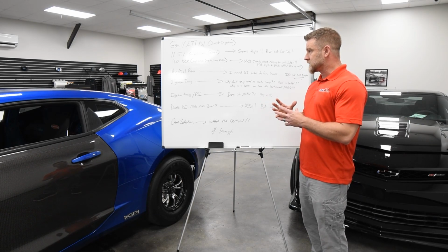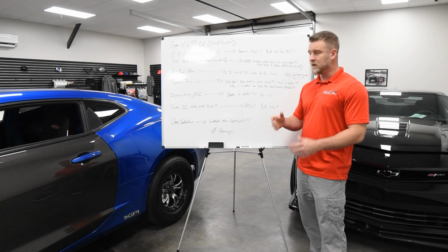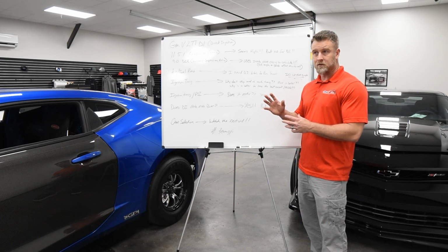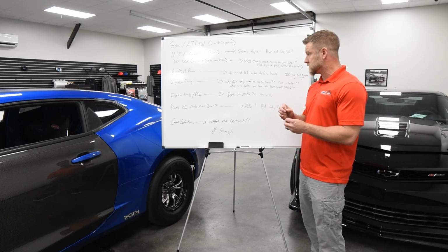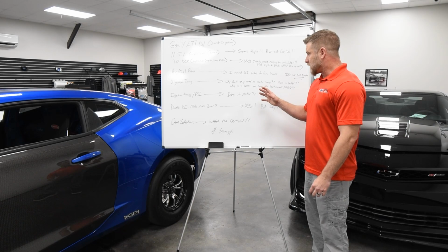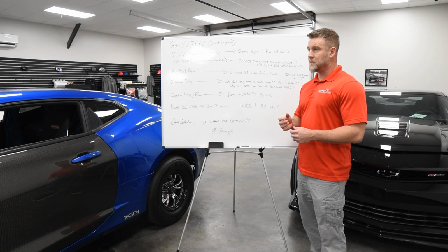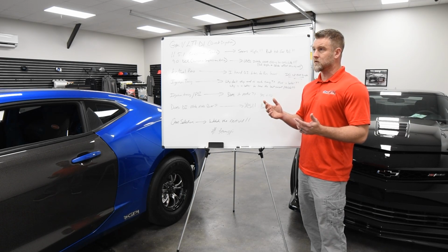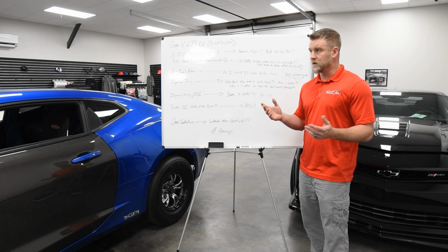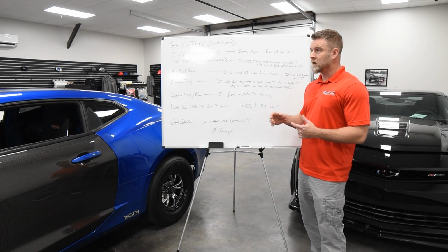When you have a package that is more efficient that you can fire later and make max power on, it's going to be better. And I'm not talking about getting abusive to the point of being way over timed, 3 or 4 degrees more timing. I'm talking about it could be just 1 or 2 degrees can make a difference in that. A lot of our LS stuff on E85, well, let's say LS3 combustion chamber, may like, depending on the compression ratio on the combo, anywhere from 28 to 30, 31, sometimes even 32 degrees, depending on the DCR and the chamber design.